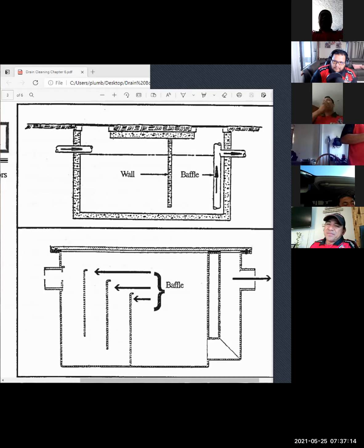Now, here's another story on ignorance. A couple of times we went back in and bypassed, went to the grease trap, connected to the dishwasher, and then for some reason they went back and tested them and found it, and we had to pay to correct it. So for me, trying to be smart and do the right thing, we got banged a couple of times financially. The answer is you cannot connect the dishwasher in Maui County. You can on Oahu. The reason? Stupidity on Maui. Oahu, smart enough to figure it out. And Maui hasn't corrected it. And the guy that put the rules in, he's long gone.